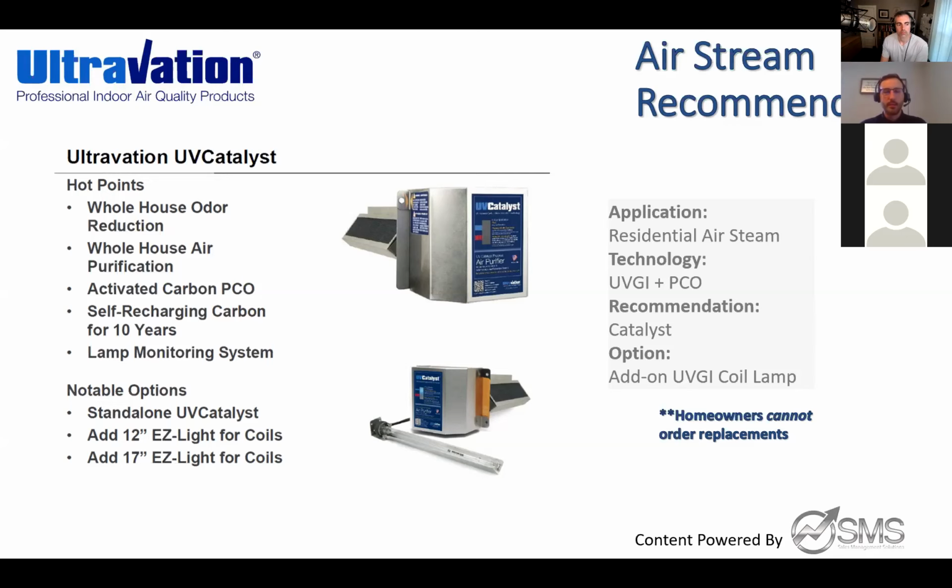Notable options: you can get just a standalone UVC Catalyst, or you have the option to add a 12-inch or a 17-inch Easy Light for coils, which basically means you have a plug and play UVC light that you plug into this and mount over your coils. We talked about the importance of airstream disinfection and coil treatment, so this allows you to do both with this product. And this product does not emit any ozone either. This product does UVGI technology, and this product does PCO technology.